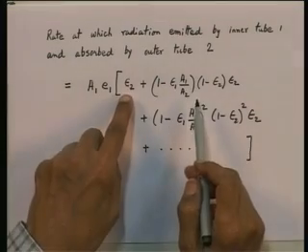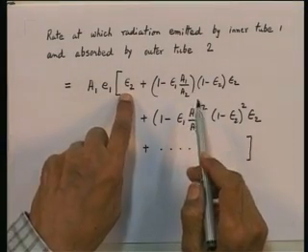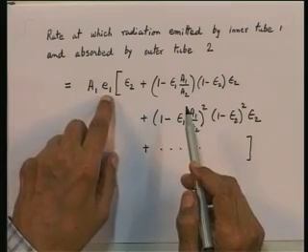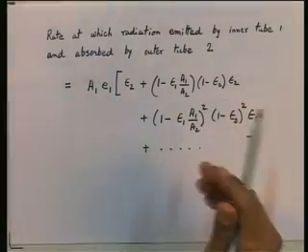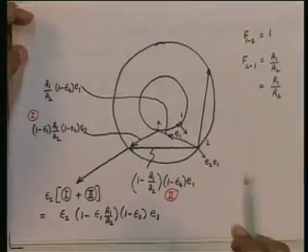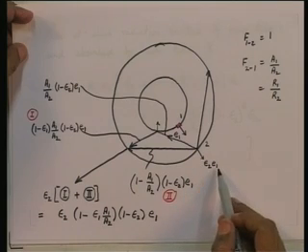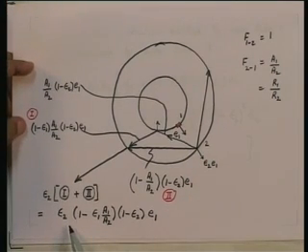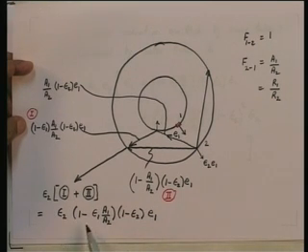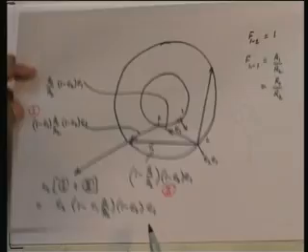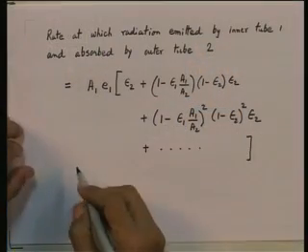So, we derived the first two terms, mind you. The first term was A1 E1 epsilon 2. Let me go back to the sketch. The first term which we derived was this one. A1, the area of the inner tube, into epsilon 2 E1. And the second term we derived was this one, for what is absorbed by surface 2, that is epsilon 2 into 1 minus epsilon 1 A1 by A2 into 1 minus epsilon 2 E1. All right. This is now very easy to sum up.